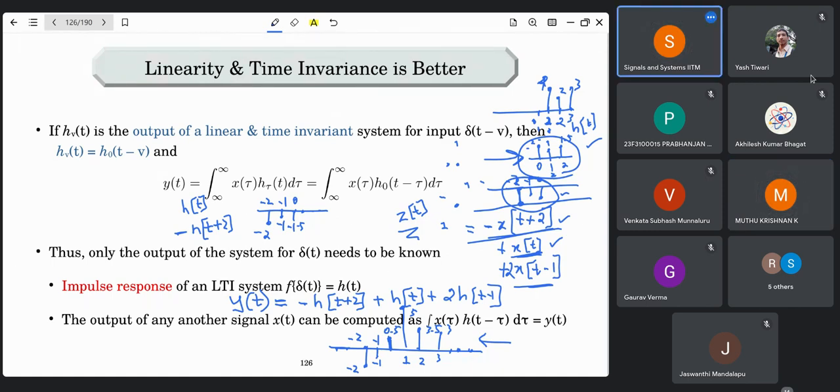One simple way is to use the unit step response. We can always get a unit step signal in real life, approximately. You just turn on the system, and from the time it is on, you can consider that the unit step has started. That is an approximation we often use in real life. You just feed in a unit step and see what the output is. That is one way of finding the response of a system. From there, you can also find the impulse response.